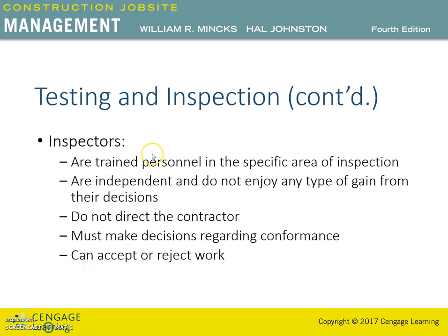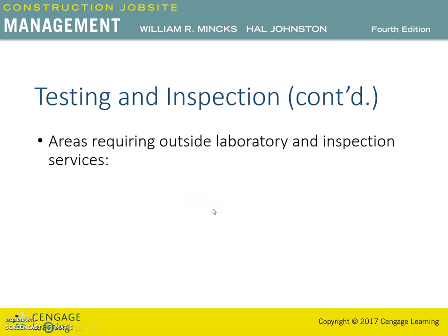So previously I described the responsibilities of the inspectors. Some of the testing and inspections have to be required from an outside laboratory, and those inspection services can be obtained, and are related with the soil and concrete testing. For example, for the compliance to the compaction density requirements. In the case of concrete, maybe the slump requirement, cylinder compressive strength.